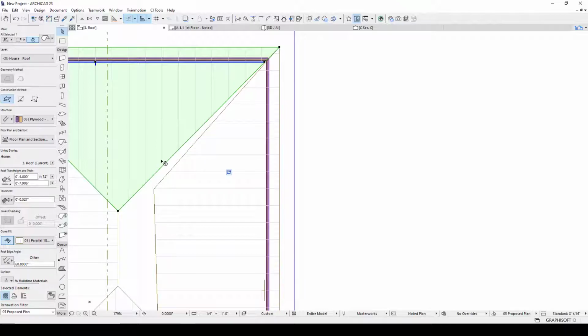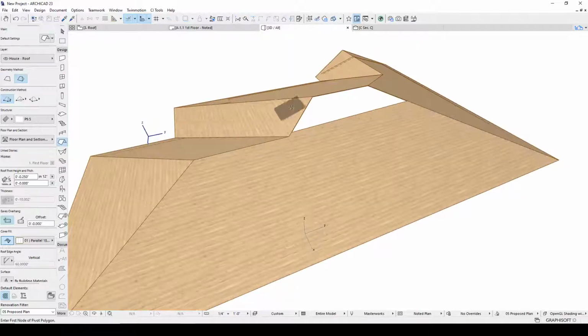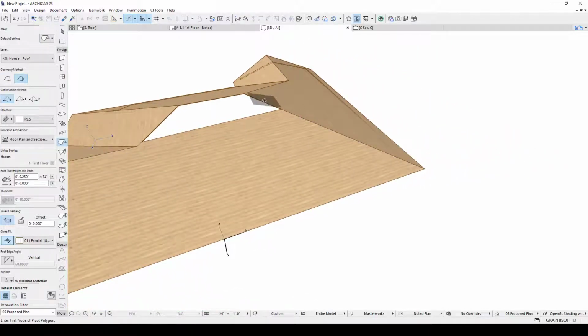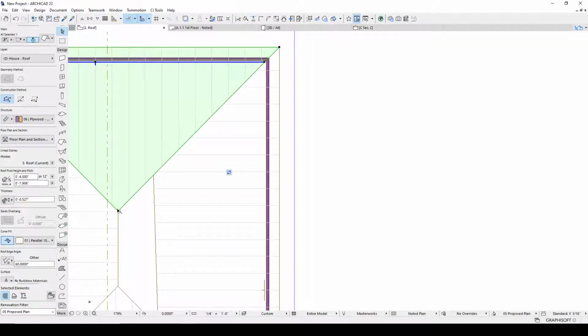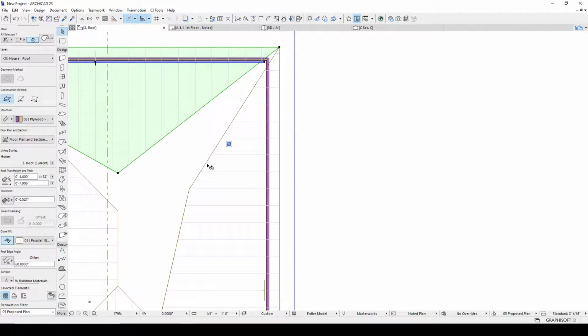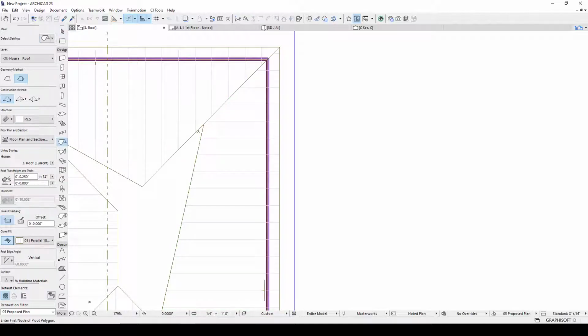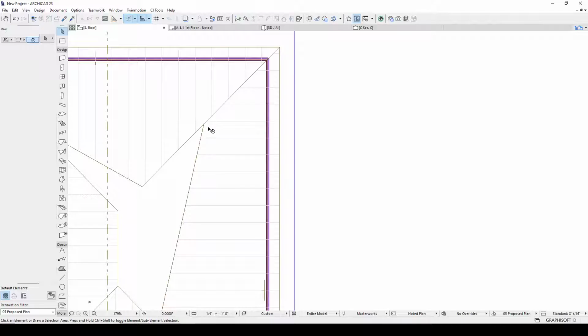Also, if I want to extend to a roof, I select the roof I want to extend to, have the roof tool selected, hit control, and it'll do an automatic extension to that roof so that these blend. But even if these roofs were both in error, they're both held back, I can select that roof, have the roof tool selected, hold control, and that's the plane that that roof should go to. I can do the same thing here, roof selected, and that'll bring that over. And so I'm healing these roofs.